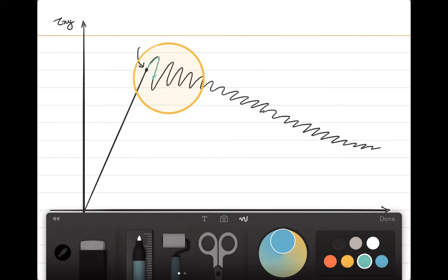So if such a situation happens and the mesh is absolutely not even close to being processable, then you would have computational problems and your analysis will terminate over here. However, in this case, of course, the mesh is not as bad. Therefore, you will have localized softening. So you will have snapback behavior, but it will also start moving towards hardening. And then you would have again release in energy and again a snapback. So you would find convergence somewhere here eventually.